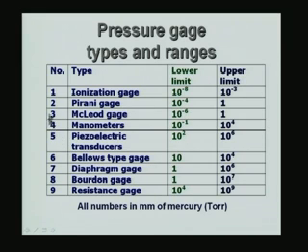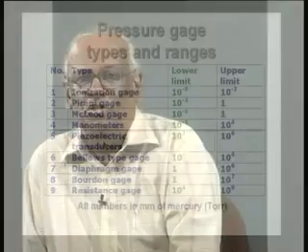Then beyond the number 4 here, we are now getting into larger and larger pressures. So, we have different types of transducers, just like we had transducers for measurement of temperature, we have transducers for measurement of pressure, and basically we have the piezoelectric transducers, which is nothing but based on piezoelectricity, application of pressure on a material produces an electrical output, and the electrical output is directly related to the pressure, and therefore, piezoelectric transducer converts directly the pressure information to an electrical signal.